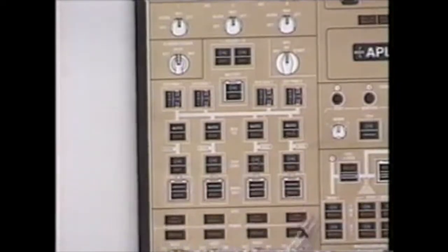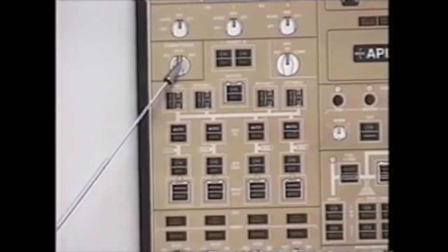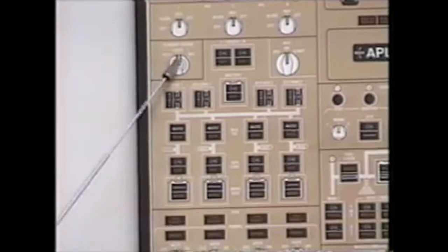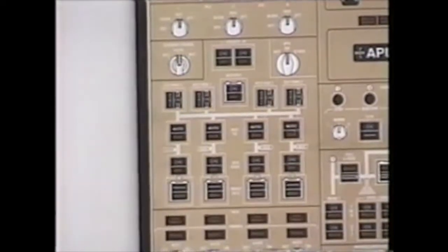Continuing our discussion with the electrical panel in the overhead, the standby power switch again controls both the APU and the main standby buses. If the airplane was fully powered with the standby power switch in auto, moving the standby power selector to off will kill both the APU and main standby buses.